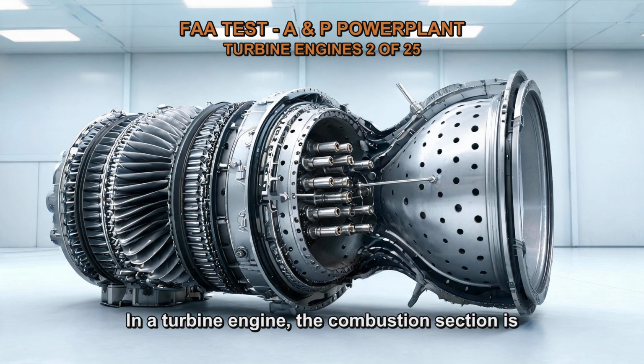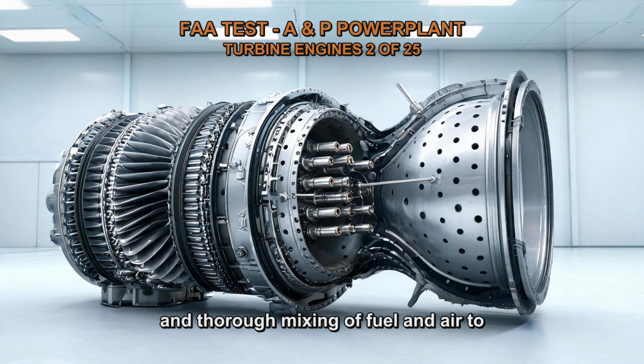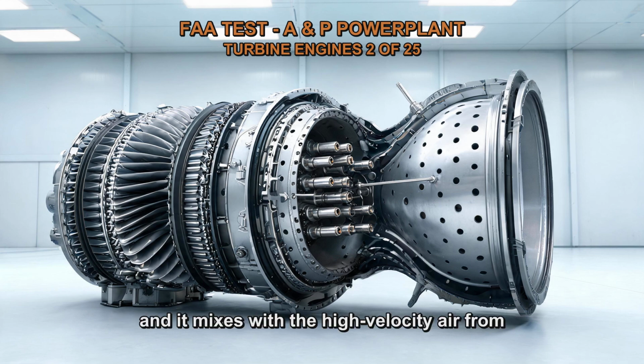In a turbine engine, the combustion section is the section responsible for proper mixing of fuel and air. It is within the combustion section that the fuel is injected and mixed with the compressed air from the compressor section, resulting in the combustion process. The combustion section is designed to ensure efficient and thorough mixing of fuel and air to facilitate combustion. The fuel is typically injected through fuel nozzles, and it mixes with the high-velocity air from the compressor.